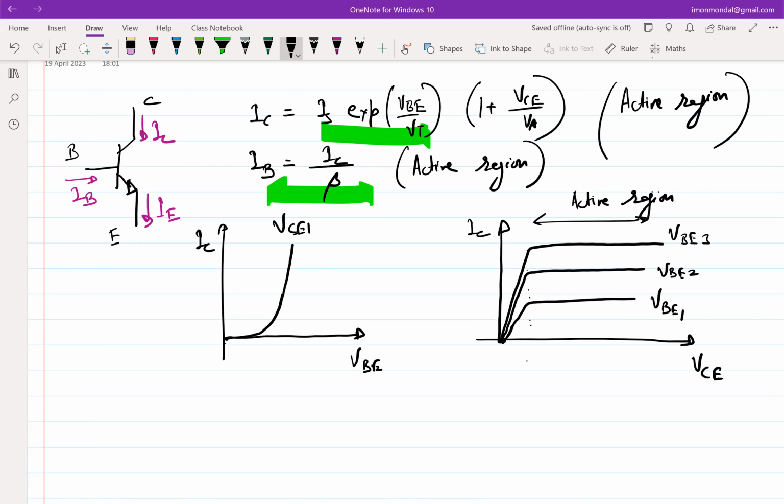But otherwise, if you just eyeball the input-output characteristics of these two devices, they look similar, which essentially means that the small signal models should also look similar, which means that all the analysis that we have learned throughout the course all apply. The only critical difference is in case of a BJT, there is an input current, which means your Y11, which we considered to be 0 in case of a MOSFET, is not 0 in this case.